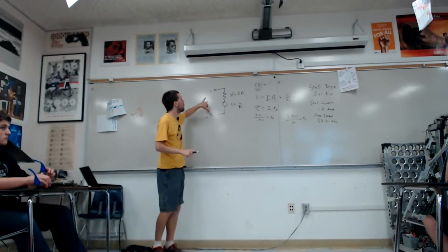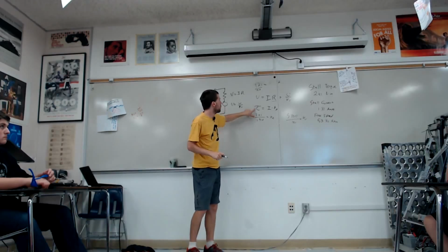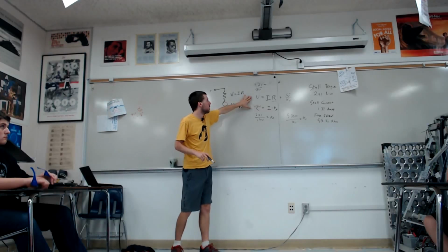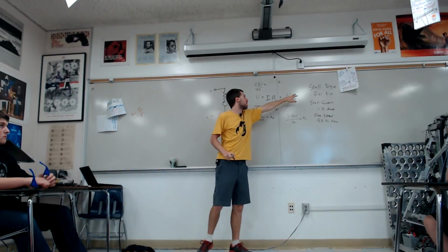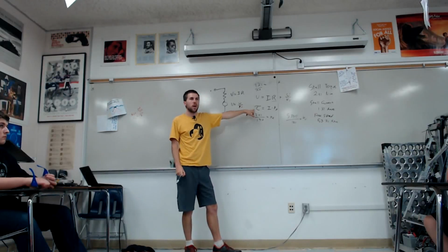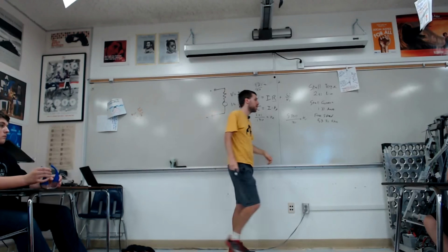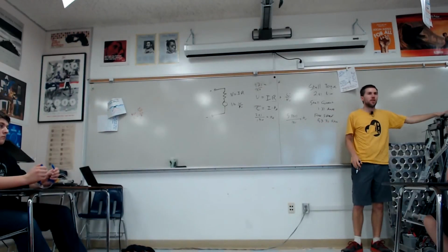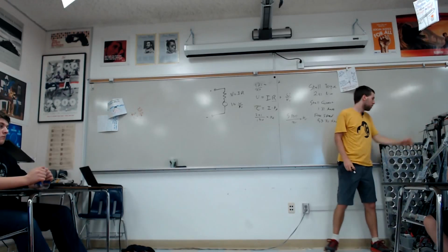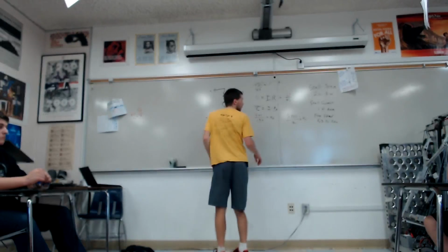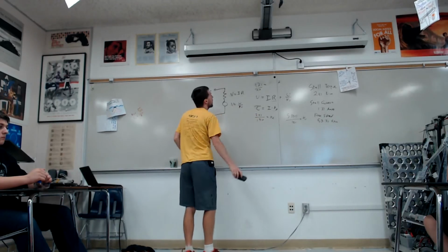Okay, so this is pretty useful. Now we can take our motor and, given a voltage and a speed, we can get out a torque. That's useful, but what we want to do next is hook our motor up to an elevator. So let's write some things down, and then we can start working out what the free body diagram for that looks like.